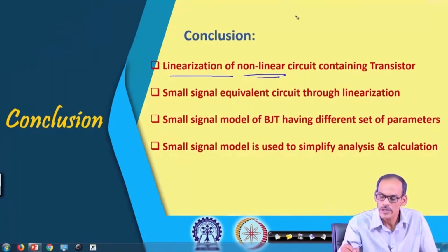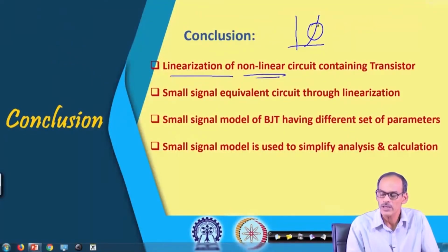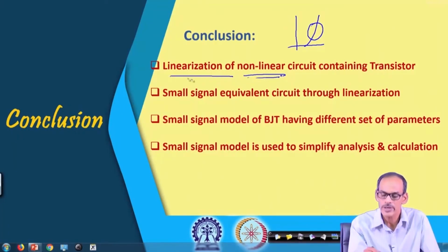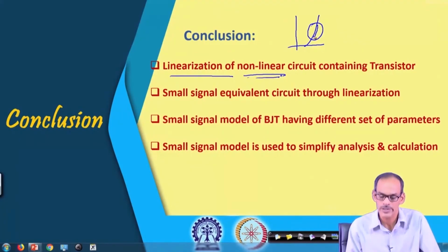So, the nonlinear behavior, say like exponential behavior, gives us highly good gain. In fact, this is one of the factors which is giving us good gain. So, we require a nonlinear circuit, but then we are looking for linear behavior, so that the output signal nature will be the same as the input signal nature.